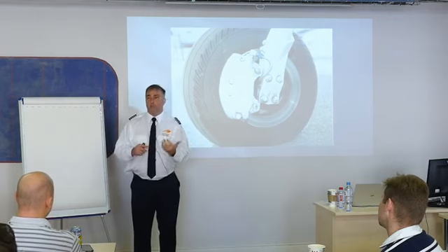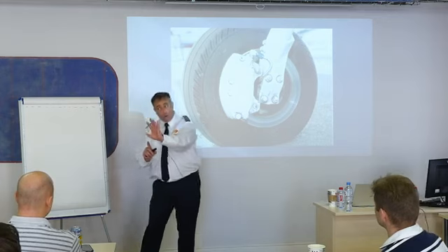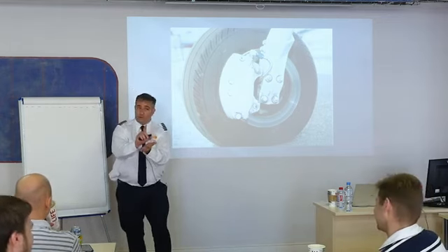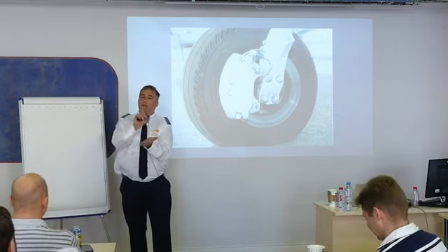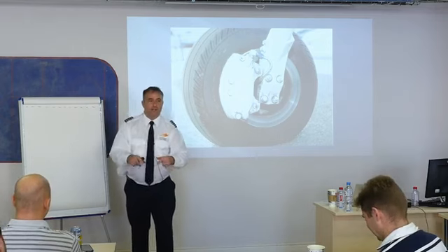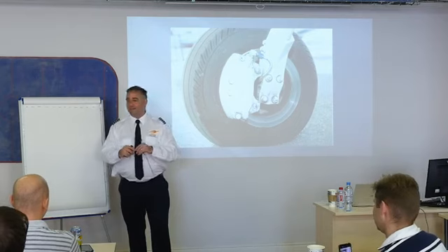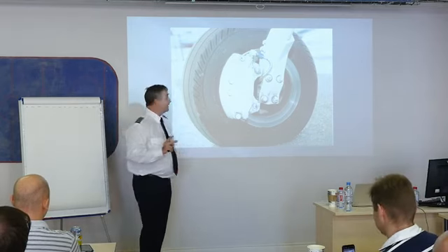Use aerodynamic braking. Make the airplane fly slower as you approach. Don't stall before you touch the ground, right? But make it slower before you approach. There's a little bit of medium ground there. Don't get on the ground and apply these brakes like you're driving a 2020 911 with anti-skid and everything. This thing does not have very good brakes at all.